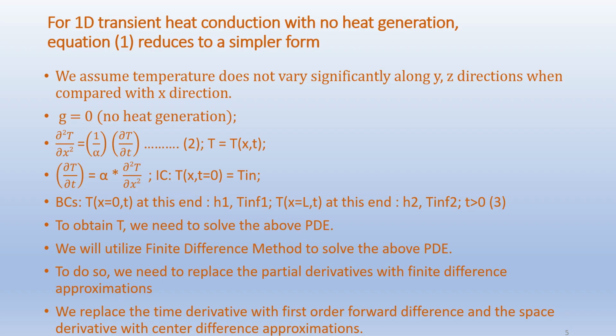To obtain the temperature profile, we need to solve the above PDE. We will utilize the finite difference method to solve the above PDE. To do so, we need to replace the partial derivatives with finite difference approximations. We will replace the time derivative with first order forward difference and the space derivative with centered difference approximations.